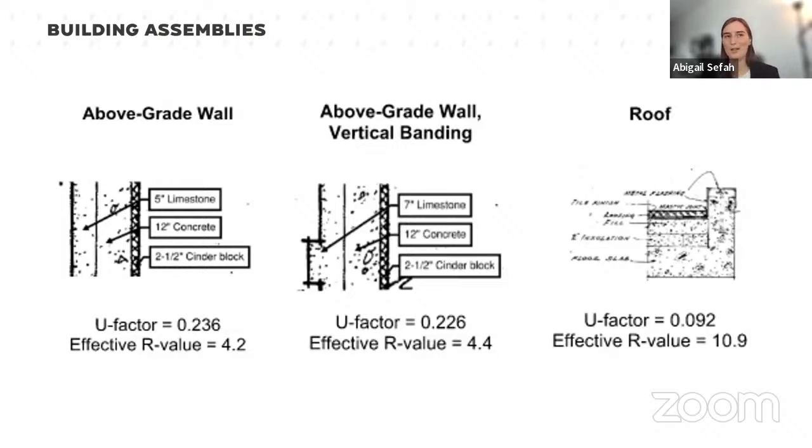And this will come back later. It's important to note that a lot of heat loss is happening at the walls, and also the majority of this building envelope area is opaque walls. There are very few windows and they're very small. They're actually only about 4% of the overall envelope area. So we knew going into this that any changes to the window assemblies would not have a drastic overall effect on overall energy performance.